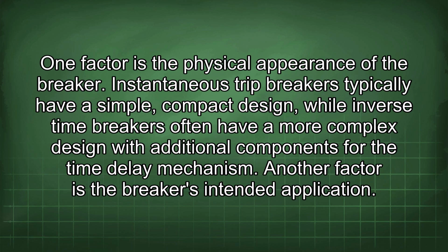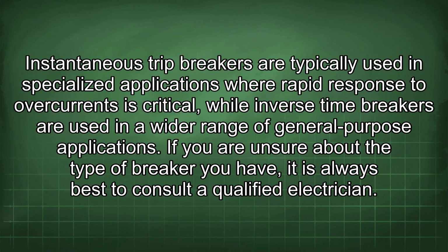One factor is the physical appearance of the breaker. Instantaneous trip breakers typically have a simple, compact design, while inverse time breakers often have a more complex design with additional components for the time delay mechanism. Another factor is the breaker's intended application. Instantaneous trip breakers are typically used in specialized applications where rapid response to overcurrents is critical, while inverse time breakers are used in a wider range of general-purpose applications.